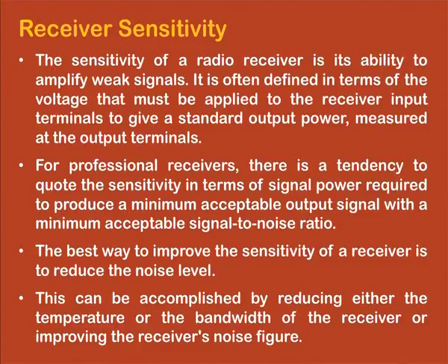The best way to improve sensitivity of a receiver is to reduce the noise level. So, how can we reduce this noise level? This typically can be done by reducing the temperature or the bandwidth of the receiver, or improving the noise figure.